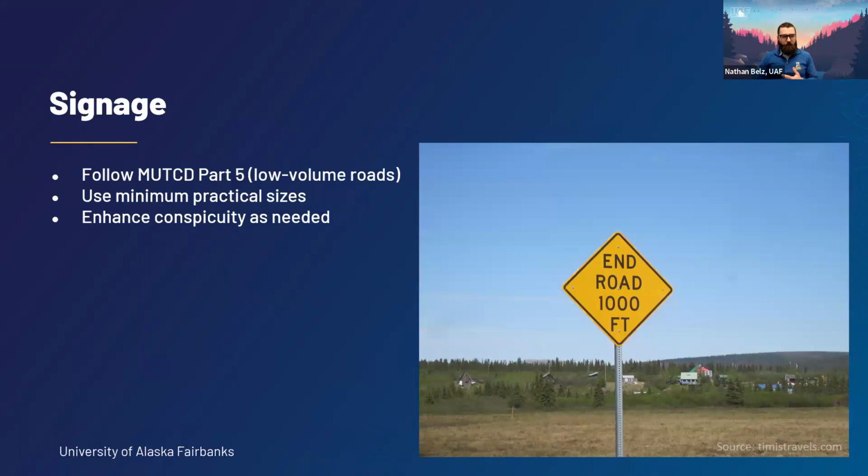As far as signage goes, signs can be an important part of road safety, but we try to keep signage to a minimum, using the minimum practical sizes as warranted. Signage is good for enhancing conspicuity.